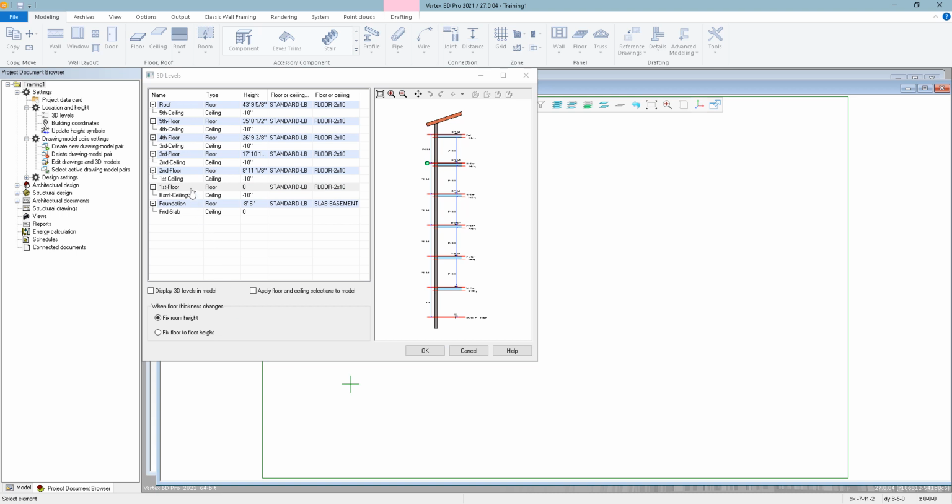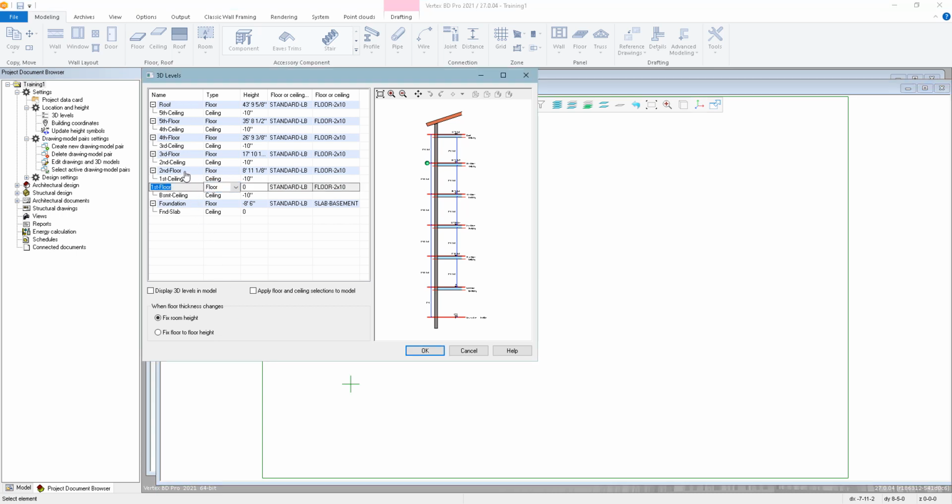The floor type height levels have been set up as main levels and can be changed freely. Ceiling type height levels are sub-levels and are located some distance away from the associated main level. The distance is equal to the total thickness of the selected floor system. If the main level changes, the sub-level will change with it while maintaining that distance.